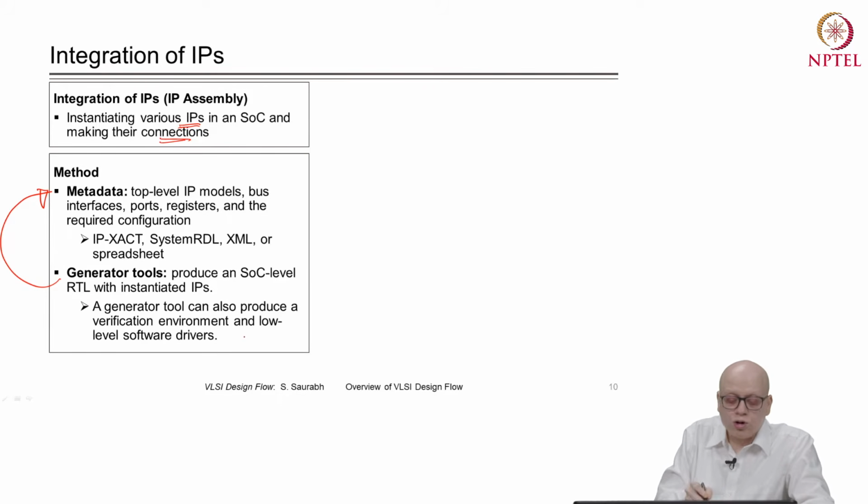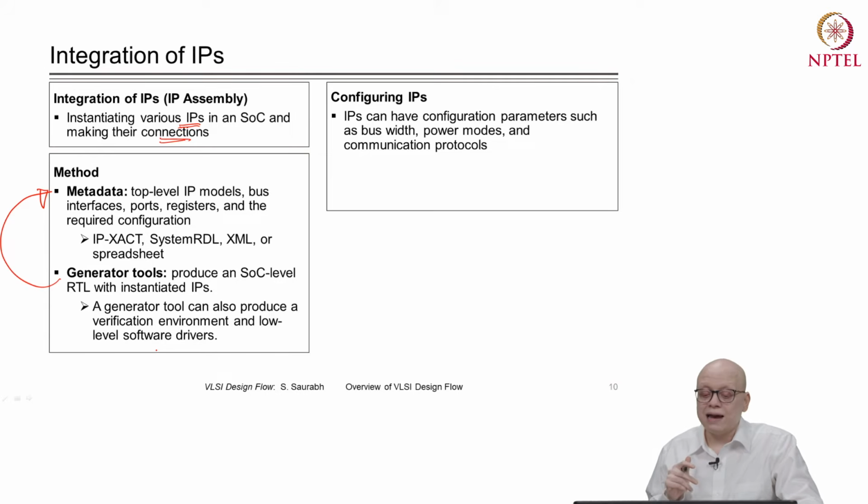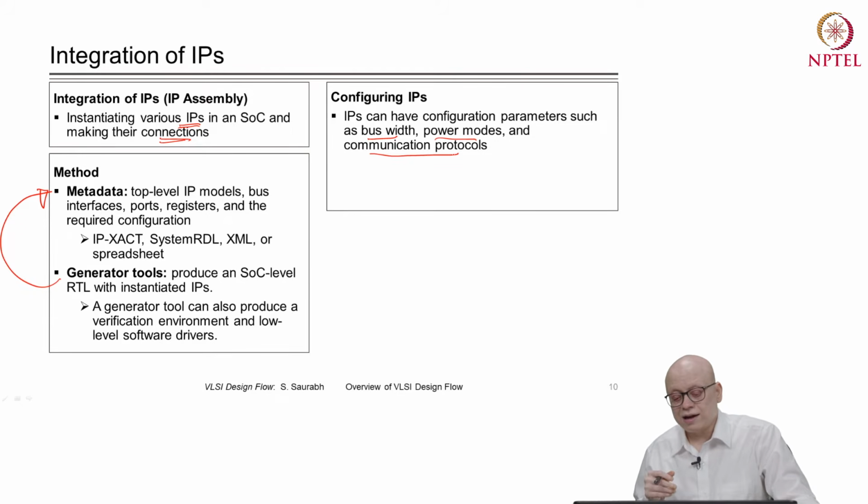A generator tool can also produce a verification environment and low level software drivers. So this can greatly help the designer and allow us to avoid mistakes in IP integration. Nevertheless, configuring IPs can be challenging, because IPs can have configuration parameters such as bus width, power modes, and communication protocols. So when we are integrating an IP in our design, what to choose for the bus width, what to choose for power modes, and so on.